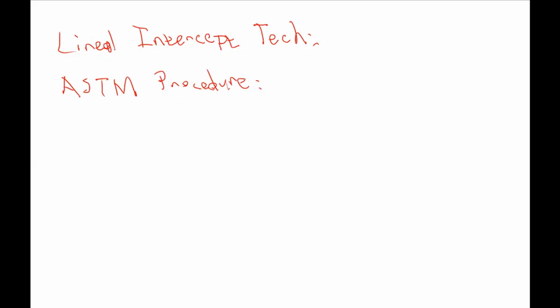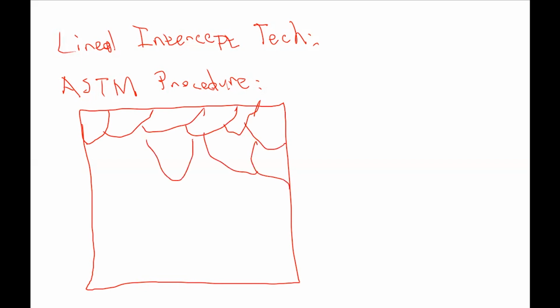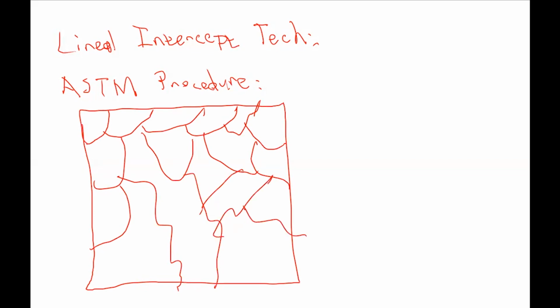So maybe in the midterm, in the exam, you will see such a figure from EBSD analysis, electron backscatter diffraction, where you can observe the grain boundaries, or even with optical microscopy, you can observe the grain boundaries and you will have such figures. And the question is, what is the average size of the grains?